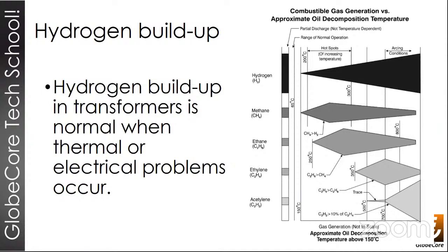If the gas is produced in large quantities, the resulting bubbles actually pose a hazard to the transformers, as they can cause electric discharges due to the poor insulating properties of the gas as compared to the oil. Hydrogen is usually associated with low intensity problems, but as you can see in this graph above, hydrogen is generated in all faults, all kinds of problems.